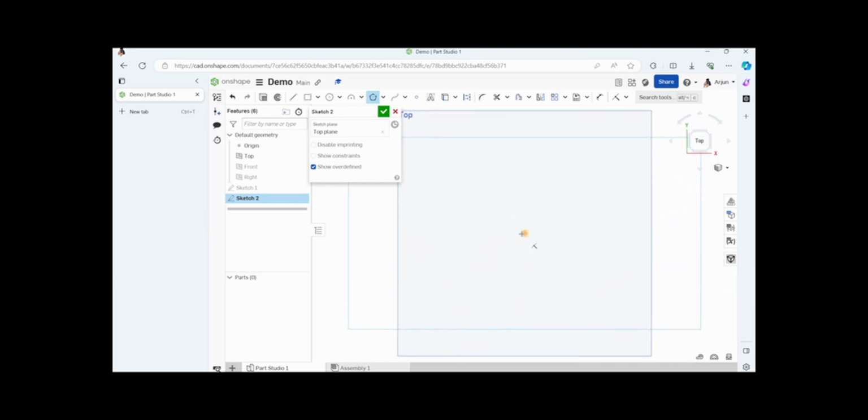So click on the center point, drag it out. I'd say like 60 millimeters is good. Well, we've got to go 6 sides first, and then let's see if we can dimension that. Okay, so each side is going to be 23 millimeters. Let's just say 25. Make it a little bit bigger. Why not?